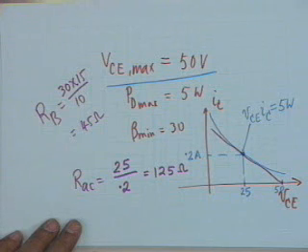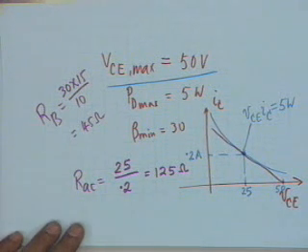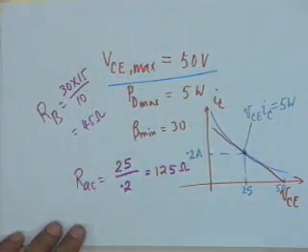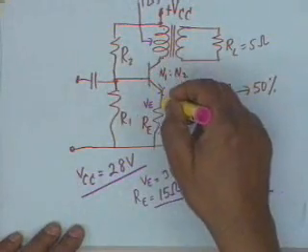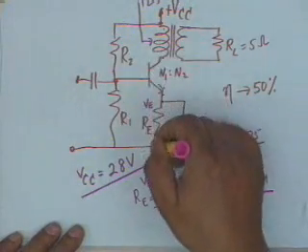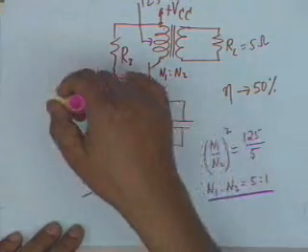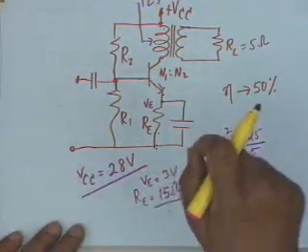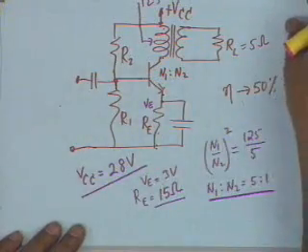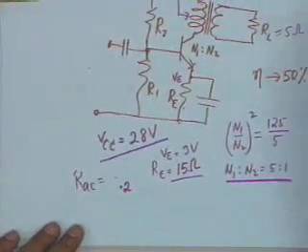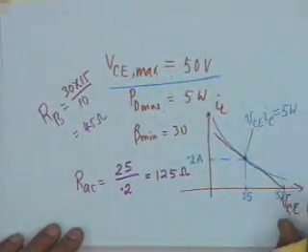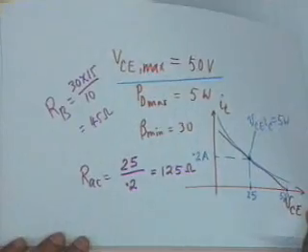All right. And you can calculate VBB from the requirement that VBE is 0.7, this voltage is 0.7, this is 3 volt, so this is 3.7. All right, VBB minus 3.7 shall be equal to IB times RB, from which you can determine RB, and therefore you can determine both R1 and R2. This calculation is routine and I shall not carry this out.